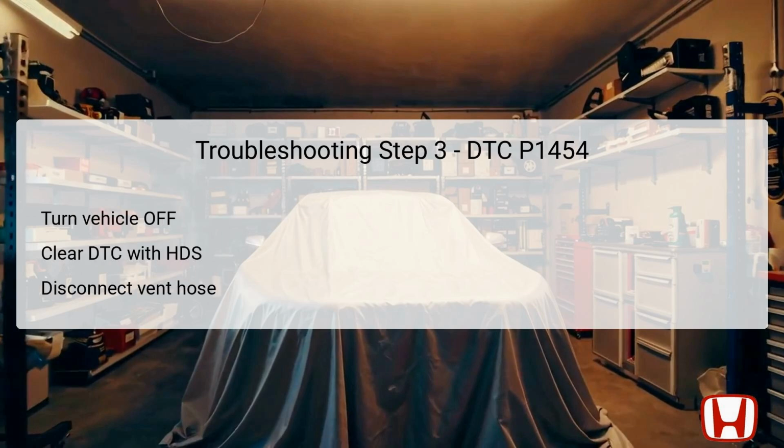In the third step, the vehicle is first turned off to ensure safety when working with components. After switching the vehicle to OFF mode, the DTC should be cleared once more using the HDS. The next crucial actions involve disconnecting the EVAP canister vent hose from the canister itself, which is essential to examine if any blockages are present.